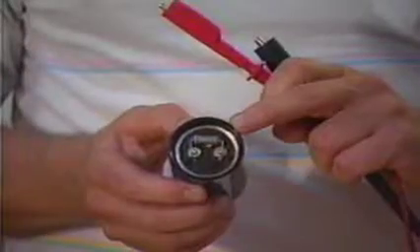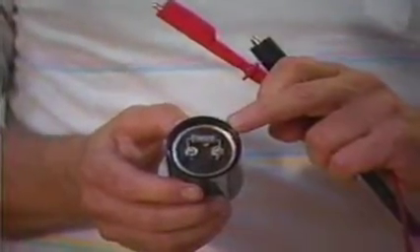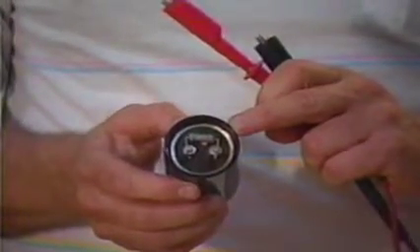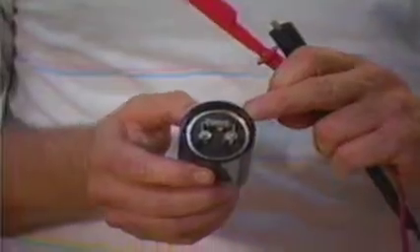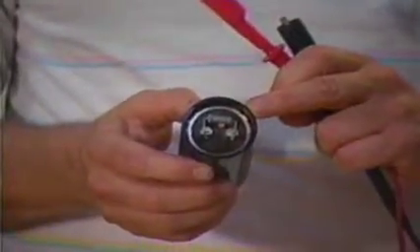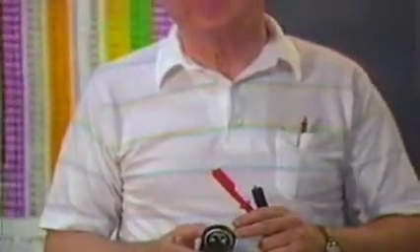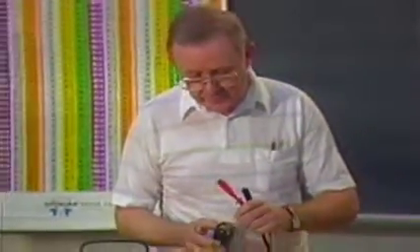Our meter is zeroed. Now this particular capacitor is a start capacitor, and if you'll notice it has a bleed resistor in the top of the capacitor. All capacitors, if they are good, will hold a charge, and it will hold a charge strong enough that if you were to apply your meter leads to the capacitor, that it could do damage to your meter. This capacitor has a bleed resistor that will bleed the charge off of the capacitor between cycles.